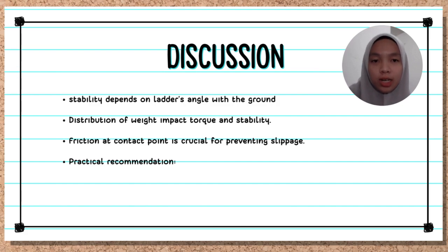Factors such as ladder height, angles, and surface friction coefficient also play a role. To maintain stability, individuals should ascend and descend slowly, face the ladder, maintain 3 points of contact, distribute weight evenly, and avoid overreaching or carrying heavy items. They should stop at least 3 rungs from the top of a straight ladder and not exceed its safe working load.